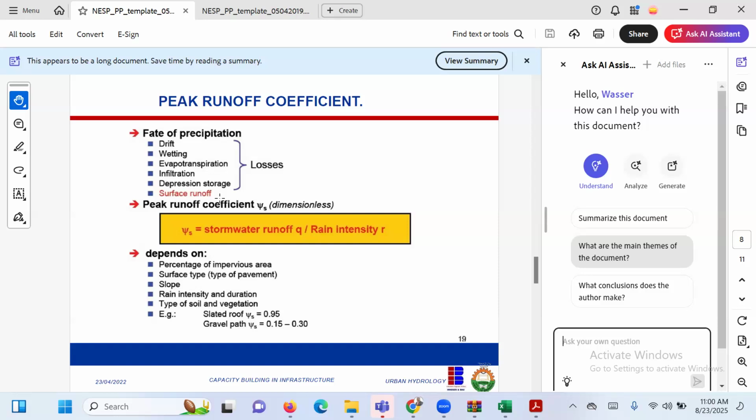So that's why in city planning, they encourage people to plant flowers and have infiltration basins. I remember those days when things were very normal. If you take your drawing to the development control in Abuja, they will want to see some level of gardening. If you pave everywhere, they will reject your drawing because they want you to provide for infiltration areas so that not all the water that falls in your plot will come to the open drainage.